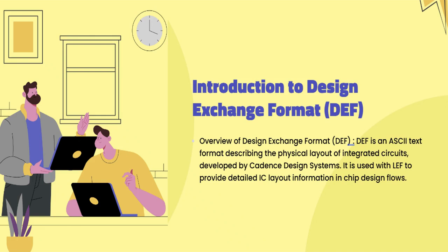That makes sense. I've heard DEF is closely linked to another format called LEF. How do these two work together, and why is this partnership essential? Great question. LEF, or Library Exchange Format, provides abstract info about standard cell libraries like their shapes and layers but not actual placements. DEF complements this by specifying the real-world locations and routes for each component, ensuring the design is manufacturable. Let's move on to DEF's internal structure.